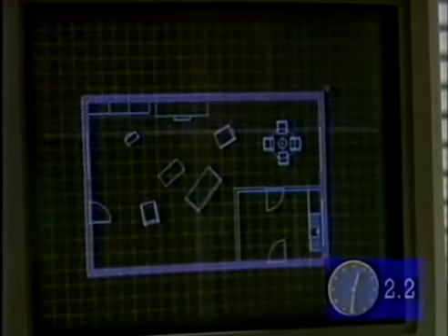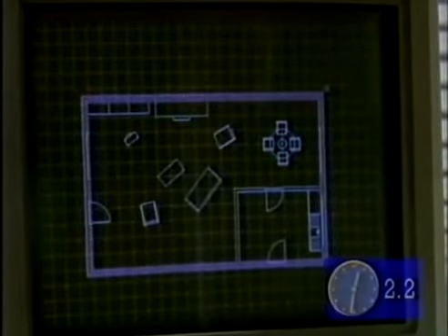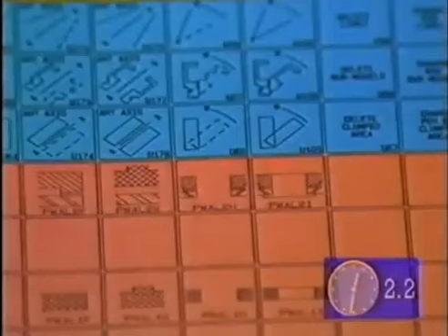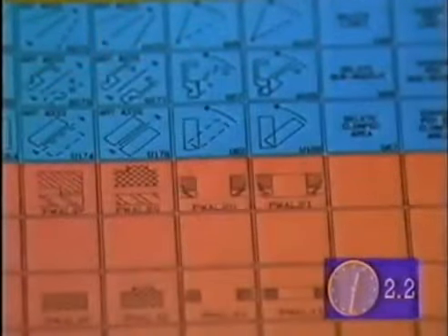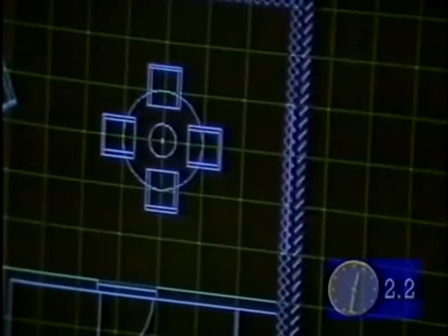There it is. Now, Peter, you've filled in the windows and the doors with brick wall. Can we get those back somehow? That's right. The actual openings are a symbol again. So we can select the symbol from the menu, and this allows us to point to the wall that we want the symbol to go into.